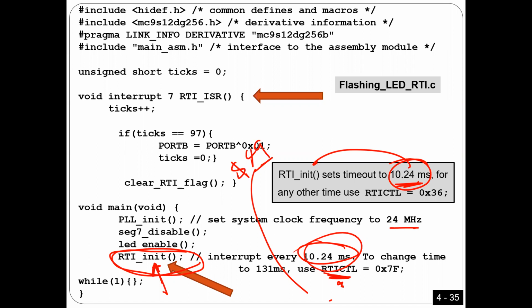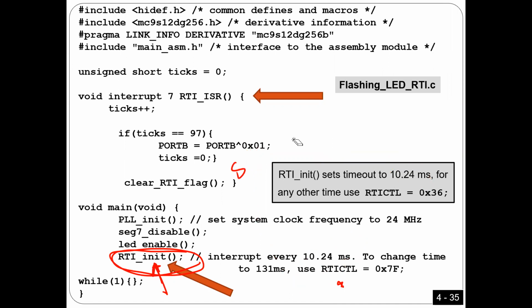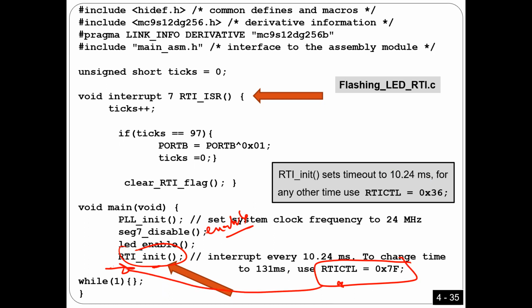Very simple. All what you have to do, guys, is after the initialization here, this initialization should enable interrupts. It should also set the time. So after initialization, you can write something like Rti equal whatever, you can put it this way. It worked with us for most of the students.